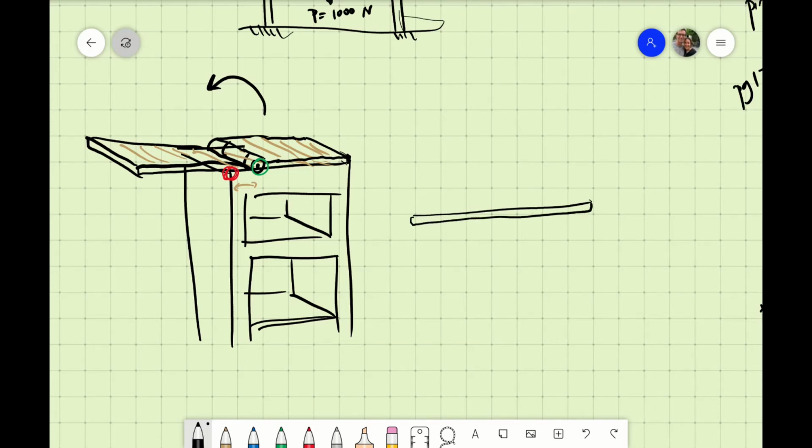something like this. You might say, okay, this is the main support. This is your hinge. It says hinge, not binge. All right, that's your hinge, and then right here, you would just have a simply supported, or if you want to call it the roller support, that's fine. I know there's no roller there. The point is that it's just resting on the thing, and there's no horizontal friction left or right.